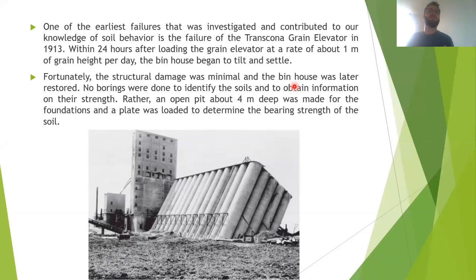And the more important thing in soil mechanics, in geotechnical engineering, is the unit weight of soil. That's soil in its natural state, so how much the soil weighs just as it is. That's usually 1.8 tons per cubic meter for soils, and if it's saturated, it's 2.2 tons per cubic meter.